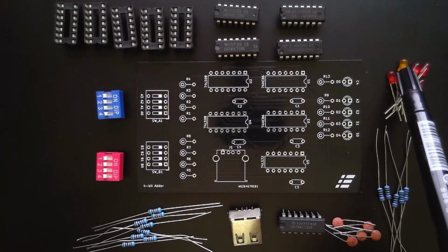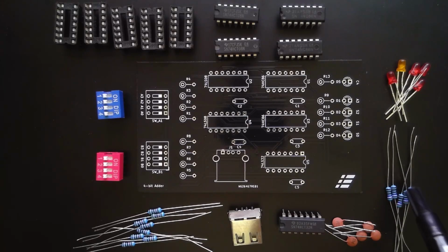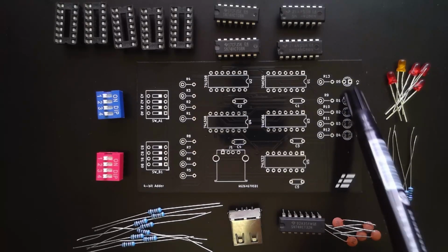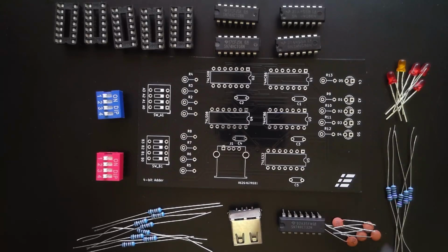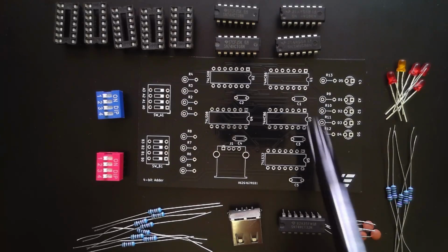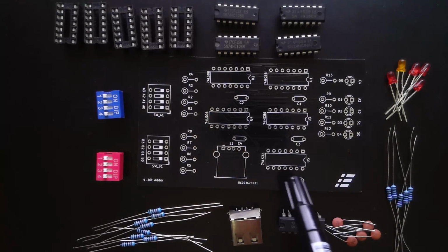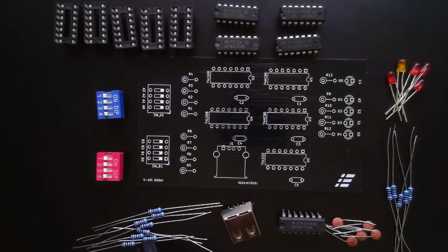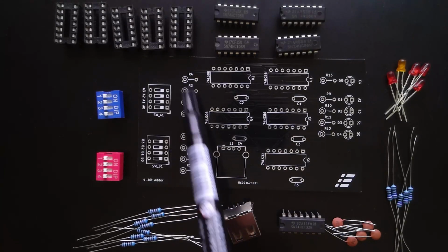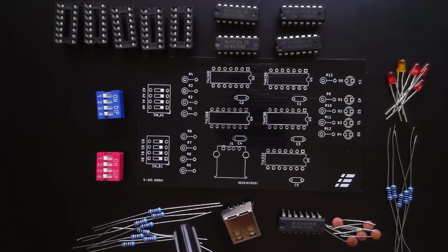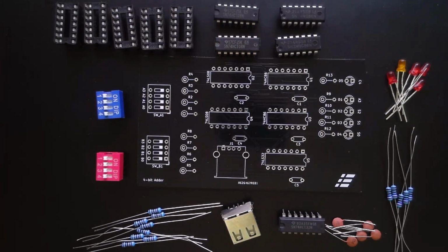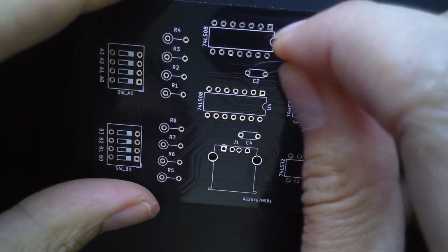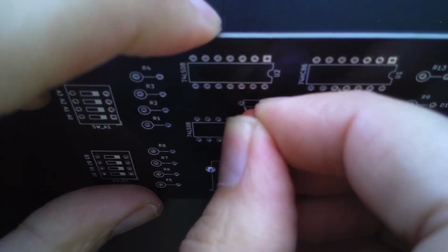We've got some little LEDs here and the current limiting resistors that we'll use for those, and they'll connect up to this section. I've got the capacitors here. They're just some small capacitors, and they'll go to each of these spots next to each of the chips where they're being powered. Got the USB connector to go in here, and then we have the pull-down resistors that will make our inputs usually 0 unless we flick the switch on. So that's all of our components, and it's time to get soldering. I'll start by soldering in all of the passive components.